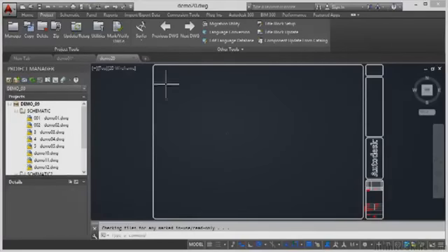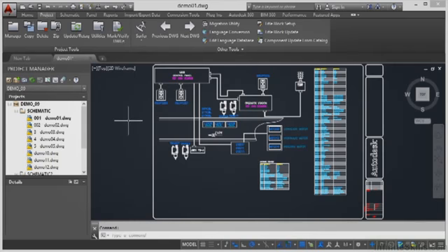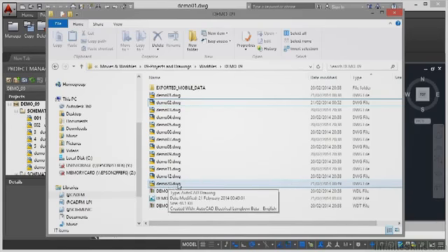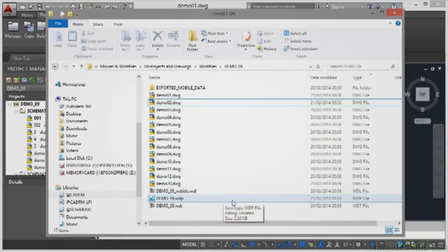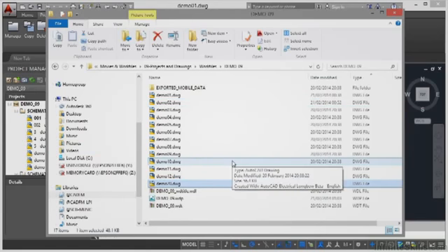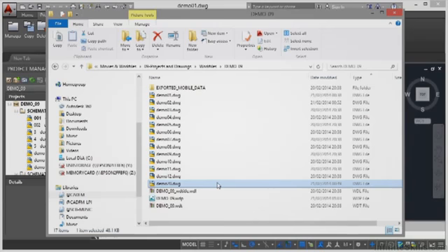That'll update it there. Notice it's still open in AutoCAD Electrical. I still need to close it here, like so. It still has to be closed. It's still a drawing in AutoCAD, even though I've removed it from the project. Now, if I go back to that project folder in Windows Explorer, Demo 20 is still there. But because I've removed it from here in the Project Manager first, I can now select it here, and I can just hit the Delete key on the keyboard.